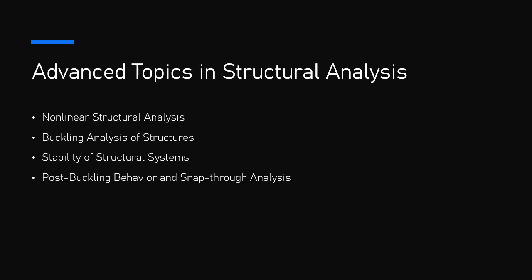2. Nonlinear stability analysis. Nonlinear stability analysis accounts for large deformations, material plasticity, and geometric nonlinearities. Unlike linear analysis, this approach can model real-world behavior under extreme loading conditions. This analysis can be performed using finite element analysis, FEA, to capture nonlinear deformations and complex interactions between forces and displacements. 3. P-delta analysis.